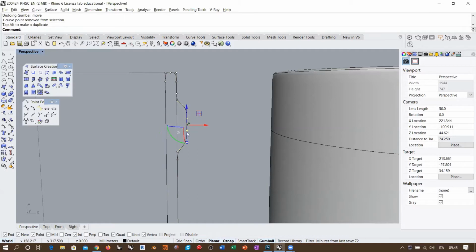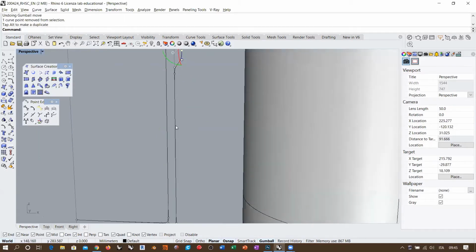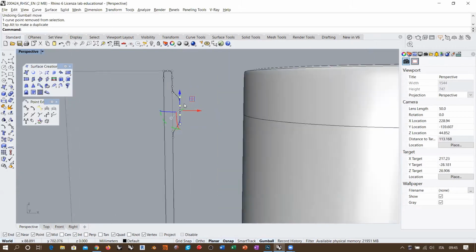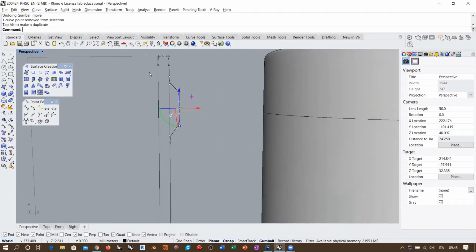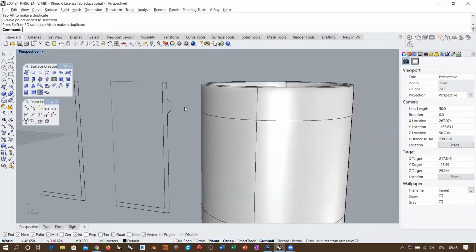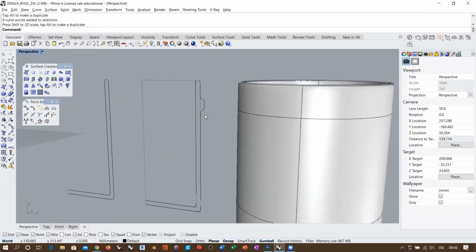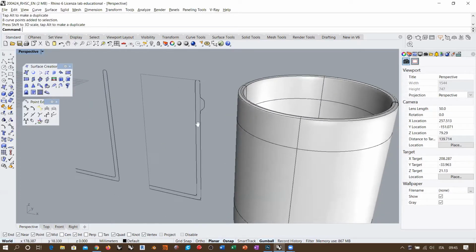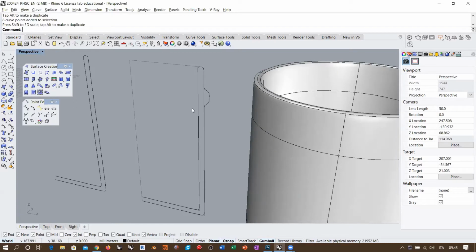So I create this flat bulge, and I go flat before reaching the top, and I go flat before reaching the bottom, okay? And of course, I can take the whole set of 8 control points here and scale them vertically if I want to reduce the shape of this bulge. If I do this, I am controlling the topology of the profile before creating the surface.